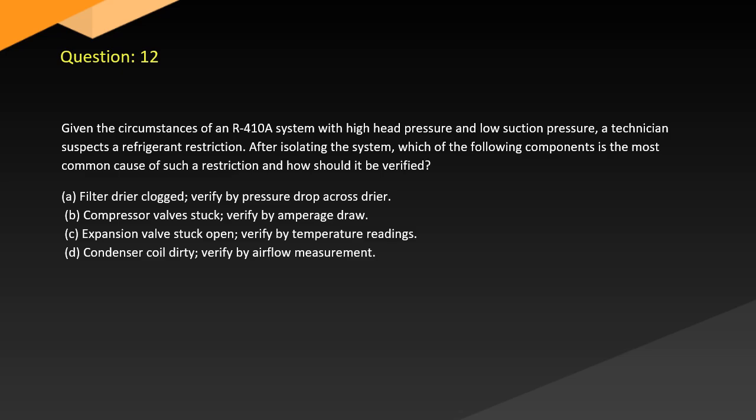A. Filter dryer clogged, verified by pressure drop across the dryer. B. Compressor valve stuck, verified by amperage draw. C. Expansion valve stuck open, verified by temperature readings. D. Condenser coil dirty, verified by airflow measurement.